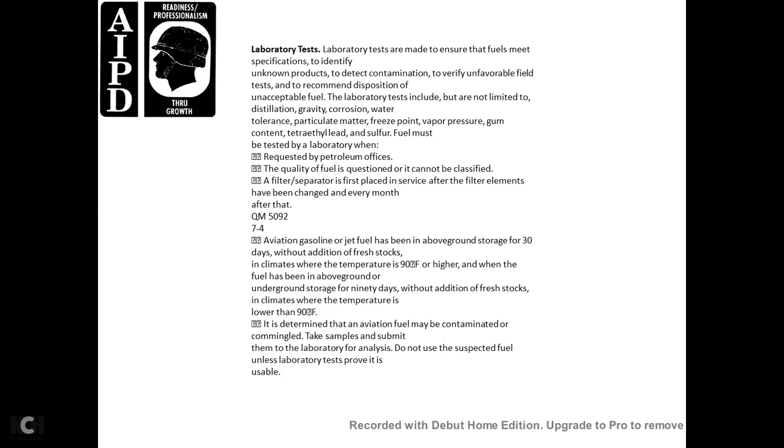Laboratory tests are made to ensure the fuel meets specification, to identify unknown problems, detect contamination, verify usable fuel, and recommend disposal of unacceptable fuel. The tests include, but are not limited to, distillation, gravity, copper corrosion, water tolerance, particulate matter, freeze point, vapor pressure, gum content, tetraethyl lead, and sulfur. Fuel must be tested in the laboratory within the time requested by the petroleum officer if its quality is in question. It cannot be classified.